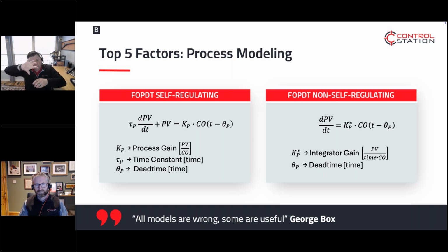But if you increase the pressure into the tank, the pressure is going to increase until the pressure equals the pressure of the line. You bleed it, and the pressure is going to drop until the pressure equals the outside pressure. And so that's an integrating process. Some density controls and batch systems are going to be integrating. So think about the dynamics.